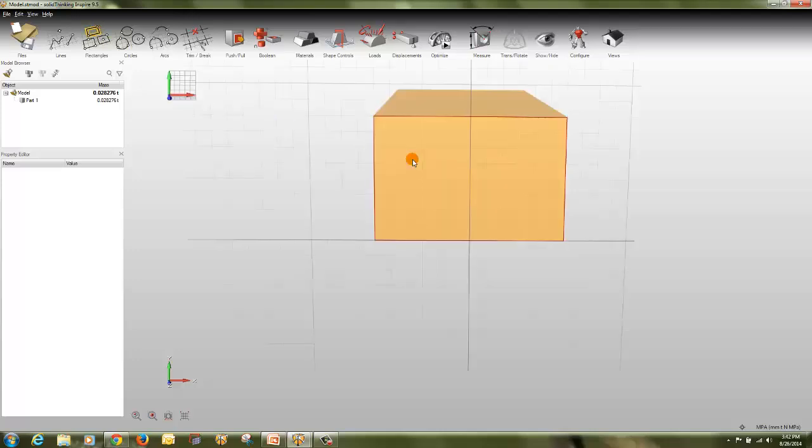Once you click it, you can see four or five options here. I'll explain what these icons are for. The first icon is sketch on a new part. This allows you to create a new part before you start sketching. Any existing sketch curve will be imprinted onto the current part before the new one is created. Now the second one is move current sketch to a new part. This allows you to retroactively move your current sketch to a new part.